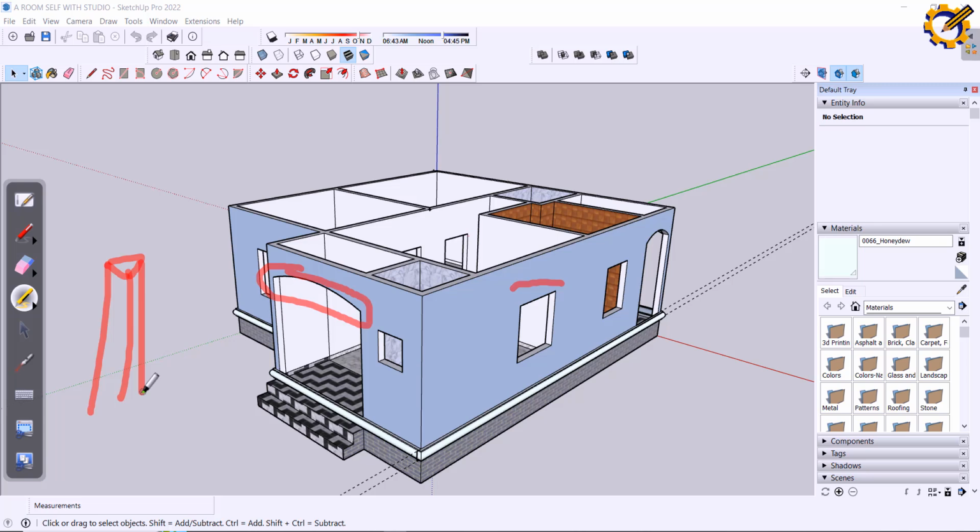So the block work is just for privacy. It's not doing anything. Do you get it now? So that is the meaning of that. The block work that they are using in such a scenario is just to ensure that the people inside have their privacy. So it is the column and the beam that are actually carrying the load there.